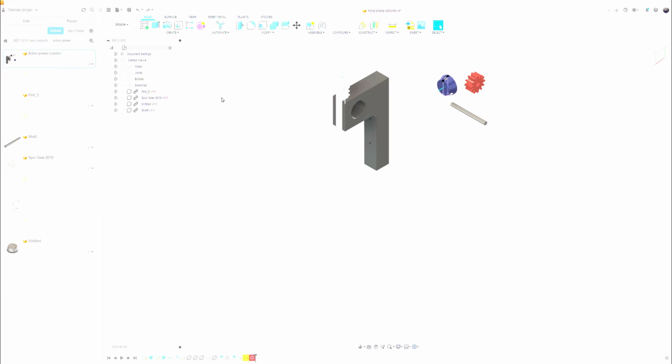So the first step is that when you're creating something that's in an existing assembly, you want to right mouse click on the top level to create a new component. If you try to create the component inside the existing assembly, you can create it as a separate object and bring it into the assembly, but you can't really create a new component by just clicking and going. You have to actually choose the new component, because it's going to create, and we'll call this cover plate.